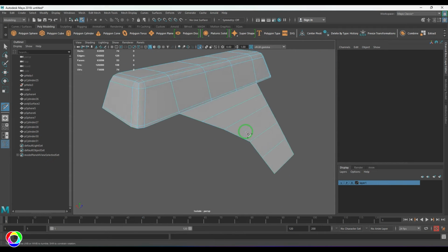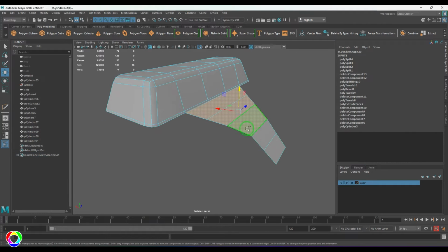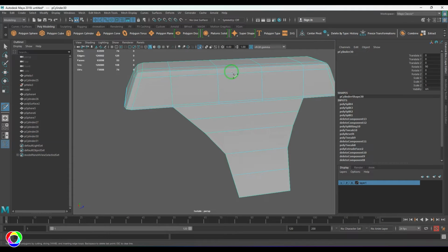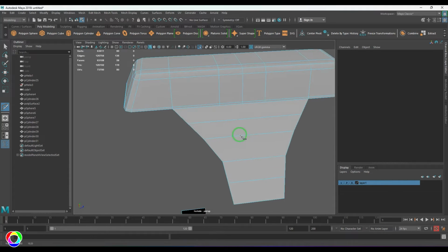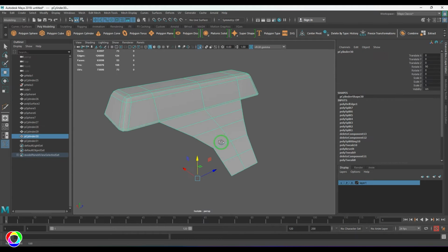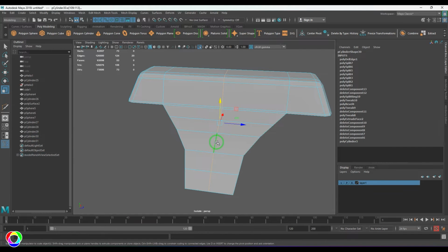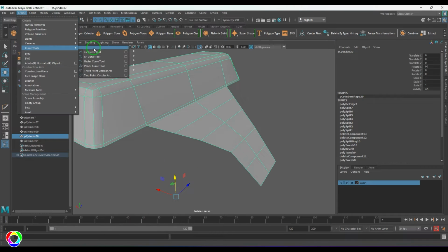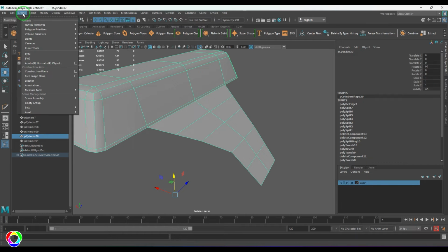Okay, so if you could see, I've got 1 2 3 4 5 subdivisions here. Let me add a line in the middle, okay, in the middle, and it's connected. And this one, I'm going to delete that. And what I'm going to do is, let me first scale it to keep it straight, and then I'll be using this tool called the arc tool. I can use 3-point circular arc or 2-point circular arc. Let me try 2-point and see if I get something out of it.